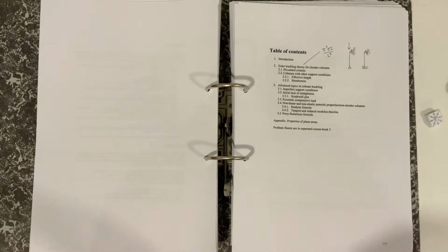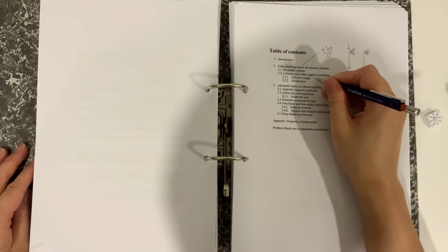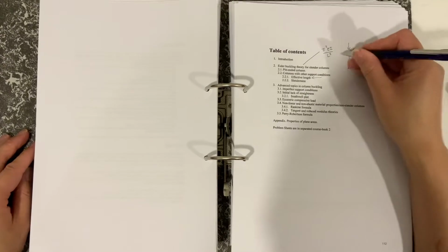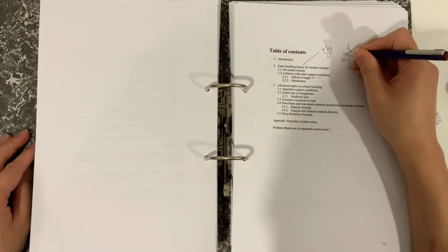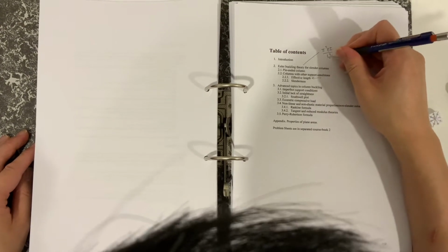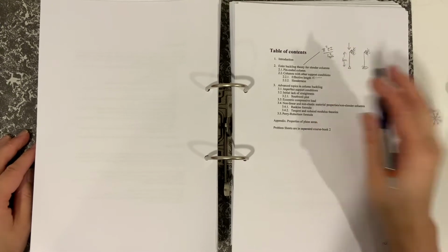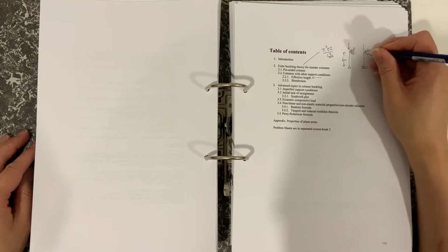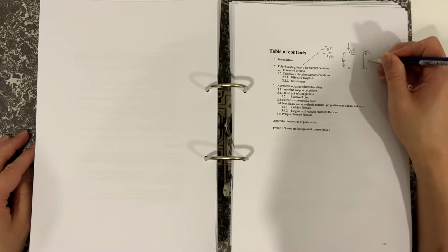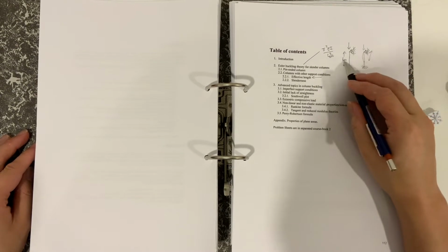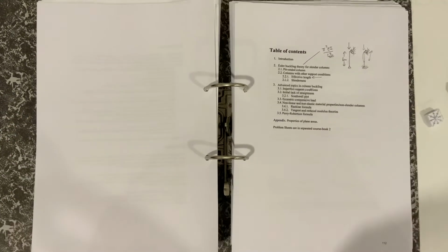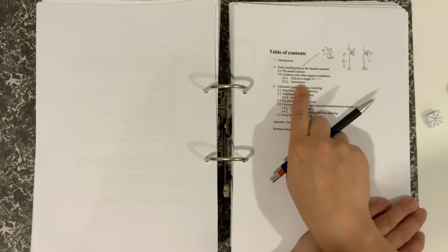Okay. And the way we handle it is this effective length. So this is pin, and if that was, say, 1 meter, the effective length to use in Euler is 1. If it was this case here, then it might buckle like that, and the effective length may be a bit shorter than 1. So we'll be using a different value, and we'll be showing from the mathematics how to get that different value. And then we'll be talking about slenderness.